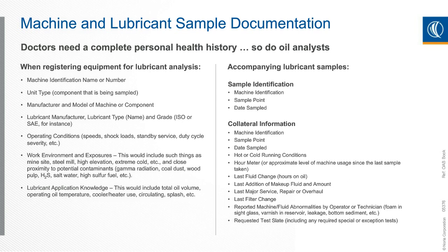And accompanying the lubricant sample, you want to make sure all the information is there so that they can give you a good interpretation of the results before it's returned back to you, when you then give the higher interpretation based on what you know about that machine.